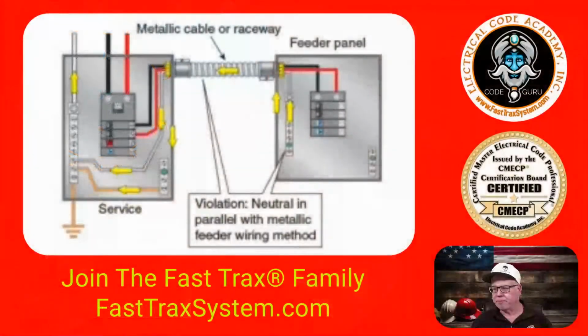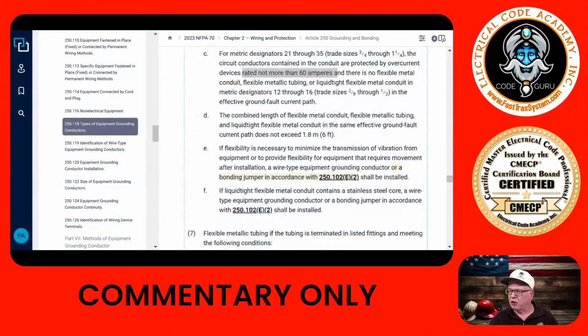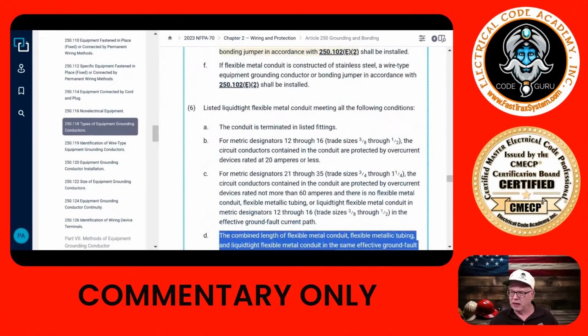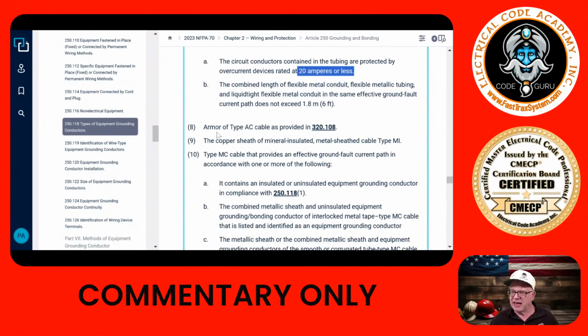All right, so let's go back to the code here. So anyway, there you go. And of course, there are length limitations as well that you have to be aware of when it comes to liquid tight flexible metal conduit. Now, what about flexible metal tubing? All right, well, can't really say that we can use this because, again, that's limited to conductors that are protected by a 20 amp or less overcurrent device, so that's not going to really play a role in our example. AC cable typically is not something that you use.